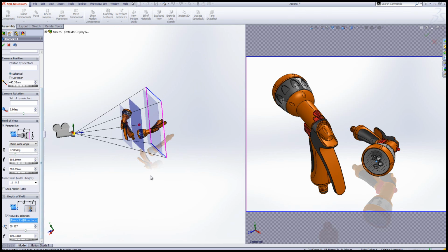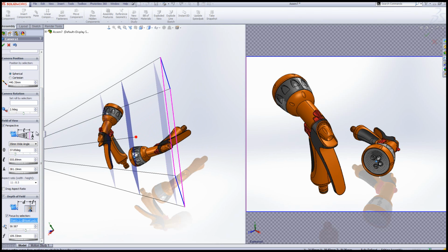Okay, so now it's just a matter of changing the f-stops, which is this plane here and this plane at the back here. It's actually set quite well, but if you want to adjust it, you can just go to the f-stop and close them or expand them. What that means is it's going to start becoming in focus around this point, be in focus here, and then start fading away to give us a nice bokeh in the background. Might just narrow that up a little bit, like so.